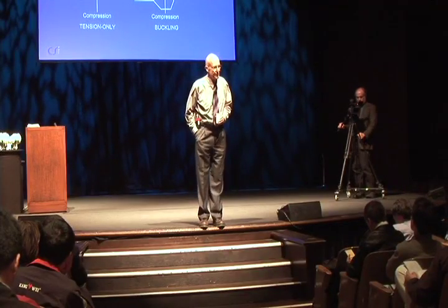But when you start the design and you say it doesn't work, what do you mean it doesn't work? The question is, is it a reasonable model for you to use for your nonlinear analysis? If you feel it's a reasonable model to use a chord rotation model, then I'd say use that. If you don't think a chord rotation model is reasonable for some reason or another, then take a look at a plastic hinge model. If you feel that is not reasonable for one reason or another, then take a look at a plastic zone model and just work down the hierarchy. Sooner or later, though, you've got to make a decision. It's got to be made.